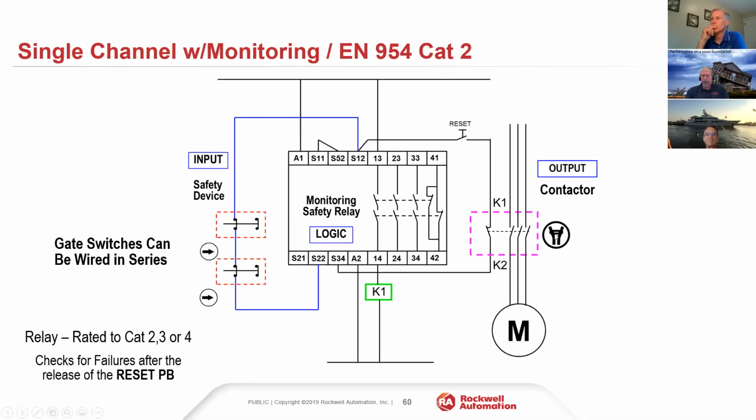And then we have a special safety contactor here, or a contactor that has safety principles applied, right? Where it's a mechanically linked or mirrored contact device. So that's an IEC contactor with that symbol, or safety contactors, etc. So what that's going to do is mechanically link the power poles with the auxiliary. And what will happen here is the reset will not function unless that auxiliary is closed. That auxiliary cannot be closed unless the main poles are open. So they're mechanically linked. So that's kind of how the circuit is going to work.